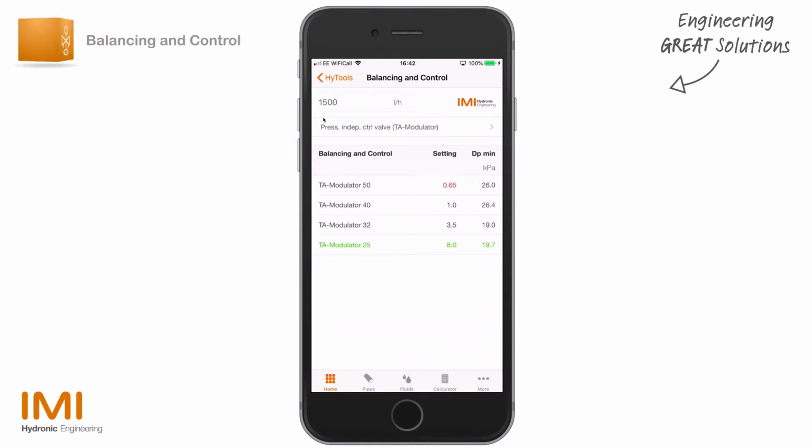So at the moment it happens to be preset to pressure independent balancing and control valves. It's giving us a TA modulator here at DN25. It's suggesting in green that this should be the correct one. And you'll see here, this is the presetting already to determine what your design flow rate should be, given the parameter that you've put in here. And it's also telling you what the minimum delta P should be on that PIBCV in order to ensure that the delta P controller is going to stabilize the flow at your parameter that you've put in here.